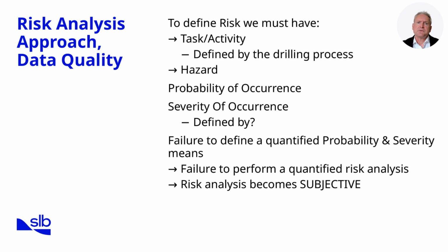To perform a meaningful risk analysis, we must start with a clear definition of both the task and the associated hazards. The task or activity is defined by the drilling process itself, whether that's tripping pipe, running casing, or circulating mud. Once the activity is defined, hazards are assessed based on two factors: the probability of occurrence and the severity of occurrence. Without quantifying both, we cannot perform a true quantitative risk analysis.